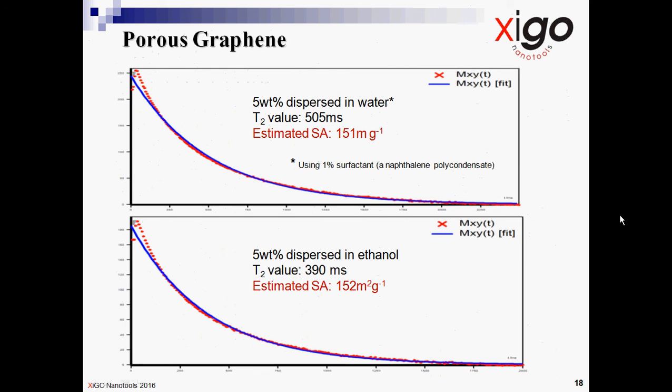Porous graphene materials, including graphene nanomesh, crumpled graphene, and graphene foam, have attracted tremendous attention and research interest, owing to their exceptional porous structure, which is high surface area, high pore volume, in combination with the inherent properties of graphene. Achieving complete wetting of porous materials, though, can be challenging. NMR liquid relaxation measurements characterize any fraction of a particle surface that is wet by a liquid, and so can be used to optimize the choice of wetting liquid or liquids.